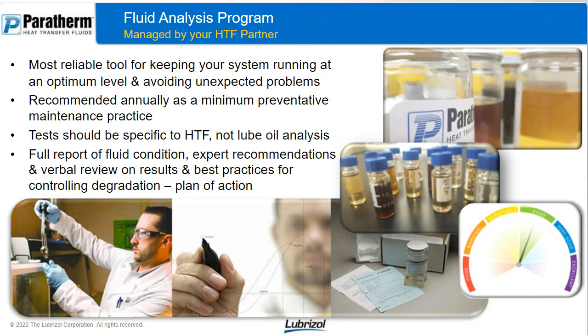That being said, make sure that your fluid analysis that you're getting on your thermal fluid is specific to thermal fluid or heat transfer fluid. Very often we see people getting fluid analysis done on a lube oil provider because it's easier to send all your fluids out to the same lab. Though they may be similar tests and similar ASTM methods, the condemning values for a thermal fluid and for any other kind of industrial oil could be very different. So you want to make sure that you're dealing with somebody who's testing based on those values specific to thermal fluid system and not just any other industrial oil.